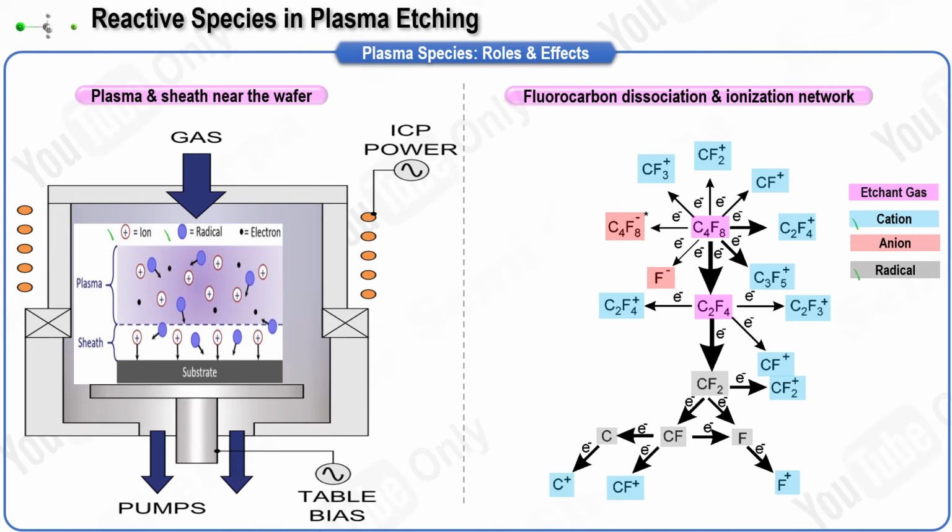These are etchant molecule gases such as Cl2, F2, HF, CF4, and SiF4. They can react at several hundred degrees, but within the normal plasma etch temperature range their direct reaction with the substrate is weak. There are limited cases where a surface pathway activates the molecule, yet in most processes the molecule is not the primary driver.